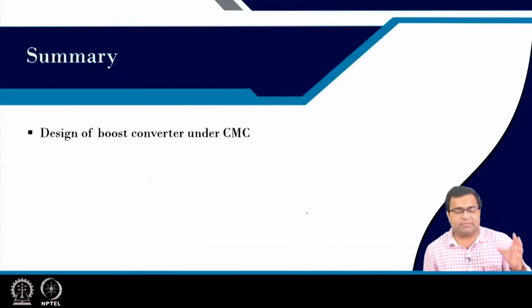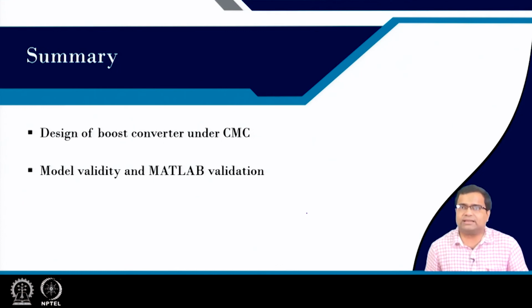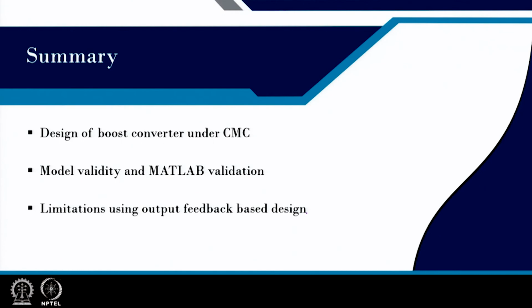So, in summary, we have discussed design of boost converter under current mode control. We checked model validity using MATLAB AC transient simulation. We have discussed limitation of output feedback based approach. We have identified what are the trade-offs, and then we have discussed how to design current mode control using state feedback based design approach.